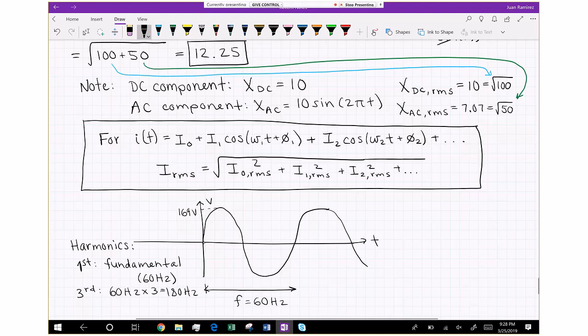So that means that the third harmonic, if we're drawing that separately, will have a frequency of 3 times that. Right over here, it'll go like this. So in one period of the fundamental frequency signal, we have 3 times as many cycles of the third harmonic.